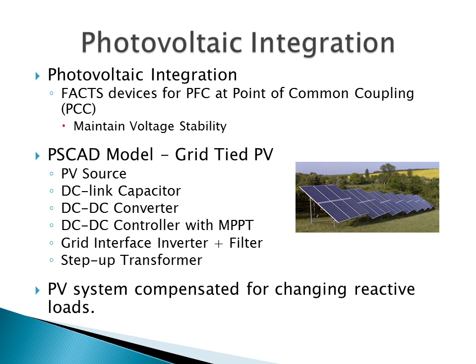When photovoltaic systems are integrated into the electrical grid, FACTS devices are needed to provide power factor correction at the point of common coupling, or PCC, the point at which the PV system connects to the electrical grid, to maintain voltage stability in the grid.